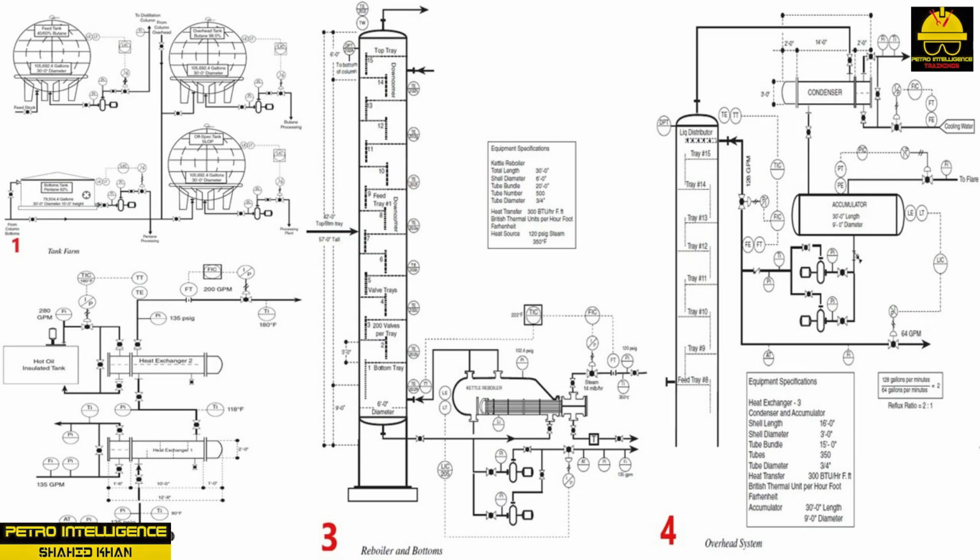In all situations, safety is always considered first, and any potential hazard is addressed prior to the startup. A distillation system is not designed to be started up in 5 minutes and producing prime product 10 minutes later. Typically, the process is started up systematically in a sequential, step-by-step process that requires attention to detail and quick reactions when necessary. The following procedure is intentionally simplistic and designed to show the basic elements of a startup. These 4 pictures illustrate a simplistic distillation system that the following procedure is attached to.